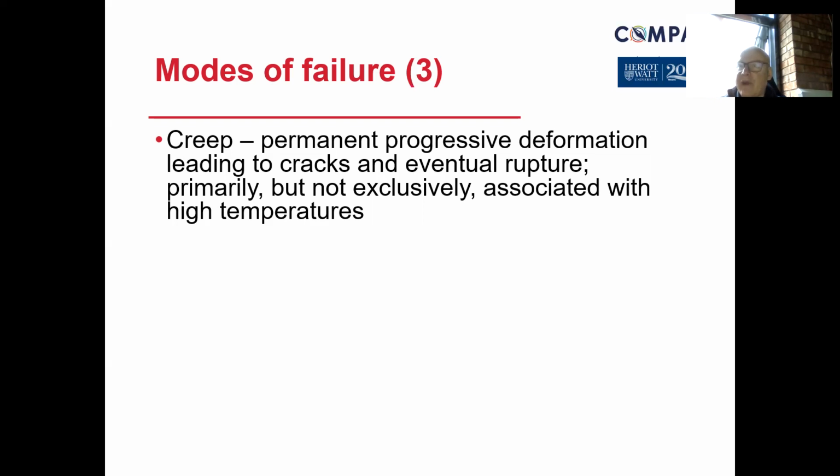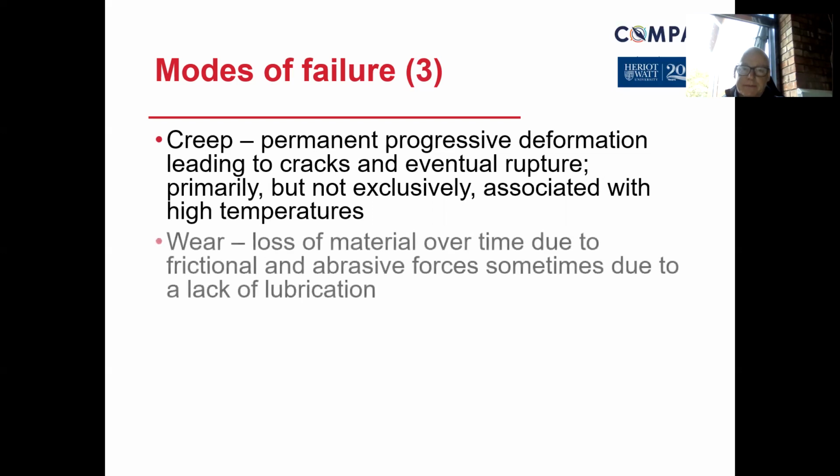So there is the need for regular visual inspections, so that you say, yep, it's still okay, it's still holding its shape, I can't see any stretching or any misshapen, so I can still use that, it remains fit for purpose. But if you see deformation, then take it out of use. The other point is that higher temperature can affect the makeup of the materials and therefore can make them softer, and creep can come in as a result of that.